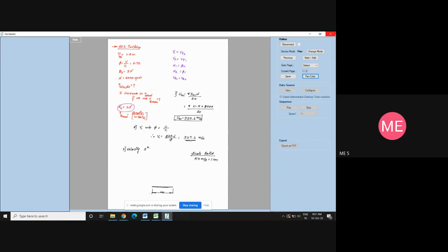UM. So you practice one thing. In the reaction turbine, you try to write down UM instead of U. That's all. And what is the line I am supposed to start from here to here? If I draw the line, it's supposed to be alpha 1. Whether alpha 1 is given in the question? No, alpha 1 is not given. But beta 2 is given, and beta 2 is equal to alpha 1. So that beta 2 is 20 degrees. From this point, I will draw 20 degrees.